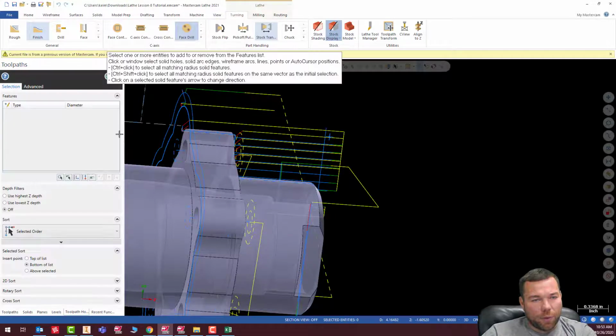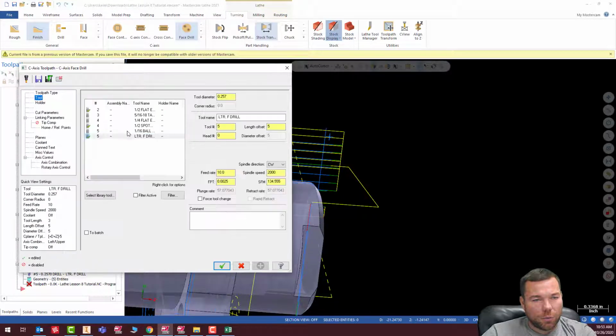Okay, now let's tap it as well. We'll pick the same holes again. Check. Tool. We're going to pick our 5/16. 800. So we just want to make sure we pick the right speed. Let's spin it at 500 RPM. And if we take 500 divided by 18, we get 27.77. It's given us, of course, the right feed rate. It should automatically calculate that feed rate for you, but I always like to double check just to make sure.